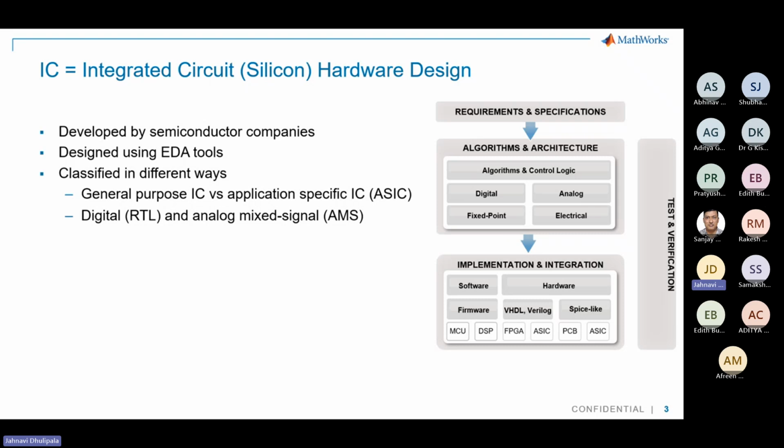After the algorithmic designs, we try to implement that in software or in hardware. Sometimes we use SystemVerilog code generation for the verification aspects. And finally, we end up deploying that in FPGAs, or we end up with ASIC modeling. So we go either by creating complete ASIC ICs, or by deploying FPGA models. And this is how the traditional workflow is.